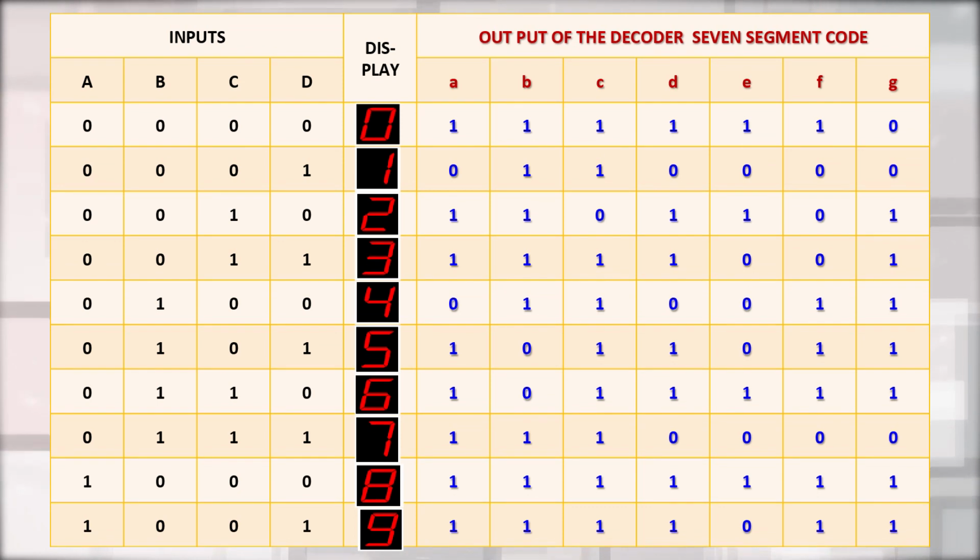The BCD to 7 segment decoder has outputs a, b, c, d up to g. So, all these outputs through resistors are connected to either common anode or common cathode 7 segment display, and accordingly this logic circuit works. For designing, we have to first consider the truth table.